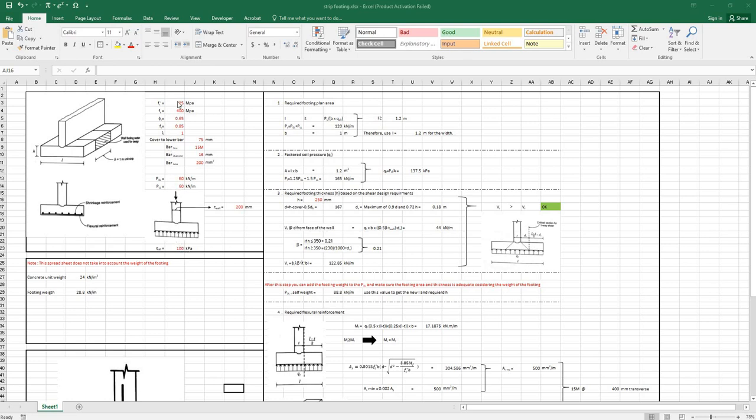You can also change information such as the specified compressive strength of the concrete, the specified yield strength of the reinforcement, the resistance factor for the concrete, the factor to account for low density concrete, the clear cover to your lower bars, the bar size that you want to use as the main flexural reinforcement, the bar diameter, and the bar area.